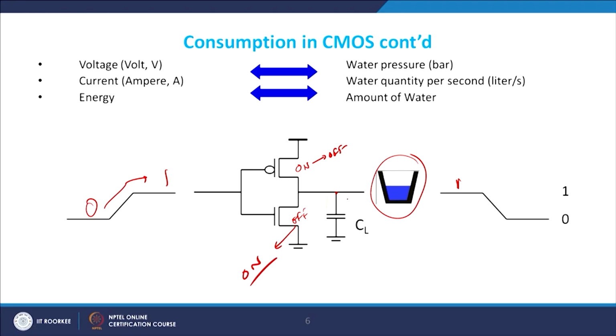Now, you see, this discharging takes place to the ground. Why is it discharging? Because now you have a low impedance path with you on the input side, and therefore you will always have this output available to you. And you see, in a CMOS inverter or a CMOS design, one very critical aspect is that your output node is typically not a floating node; it is either connected to VDD or connected to ground. That is quite an important observation at this point of time, without going into further details of it.